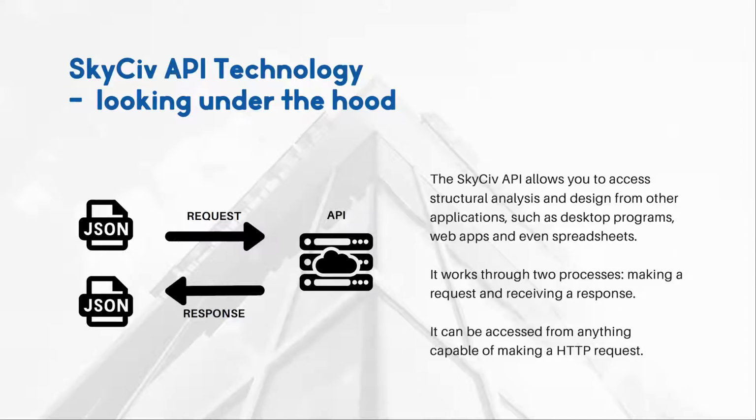So we can set the model, we can save it, we can run an analysis, things like that. Then we send that over to the SkyCiv server, and the SkyCiv server comes back with another JSON that includes a load of information about what's been done and the results that have been found. Pretty much any technology that allows you to make an HTTP request will let you do this. That could be a desktop program, a web application, as in the case of MT Solar, or in fact just a spreadsheet as well.